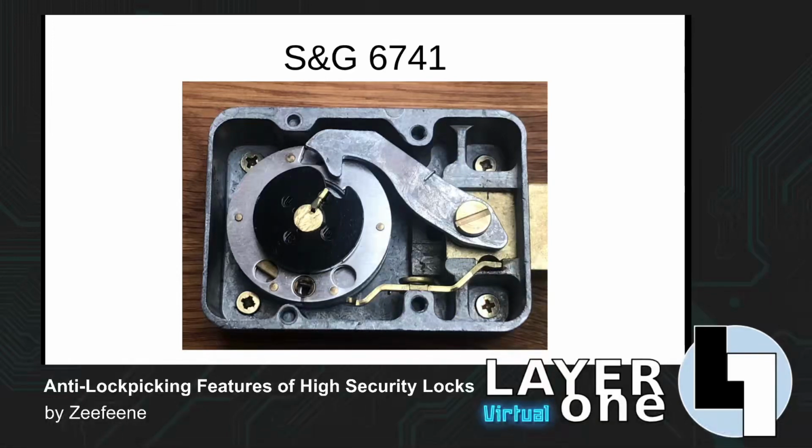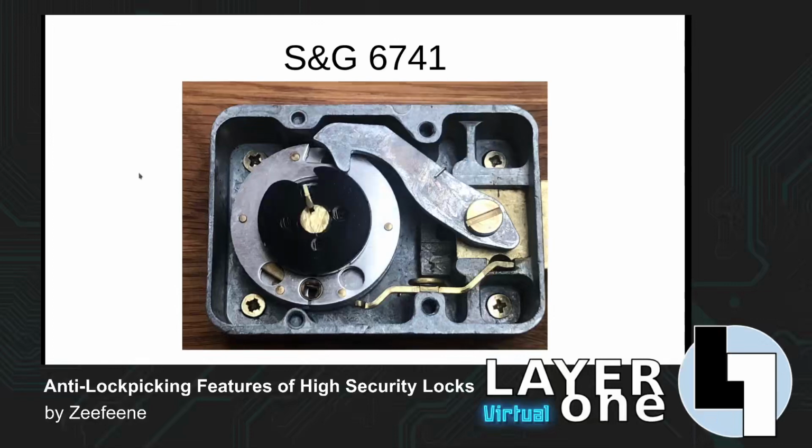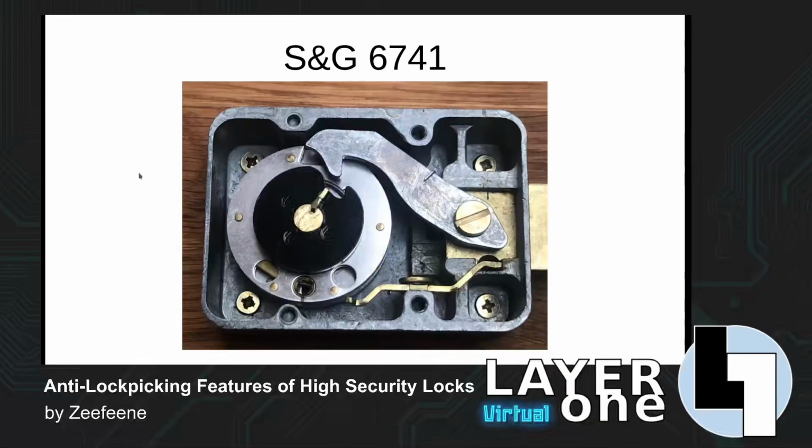And when the gates in those wheels are correctly aligned underneath this nose portion, then it can drop in and open the lock. And you might have noticed that there's a little corner of a spring here on this lever, and that constantly biases the lever against the wheels, so the mechanism is constantly under tension. But the problem that we do have is this black portion, and forgive the fact that the camera angle changes slightly here,